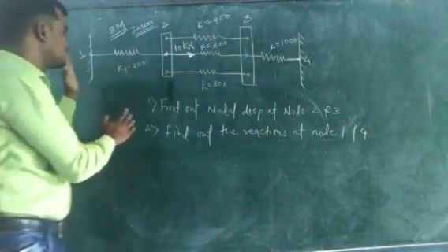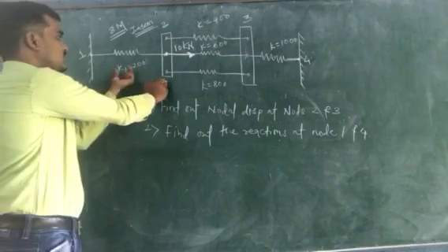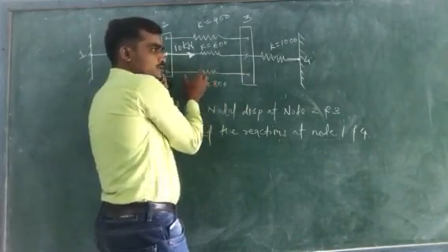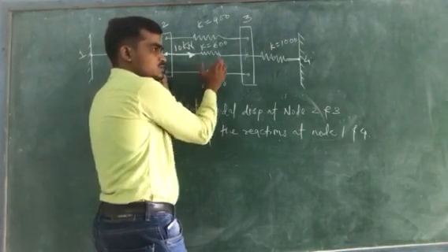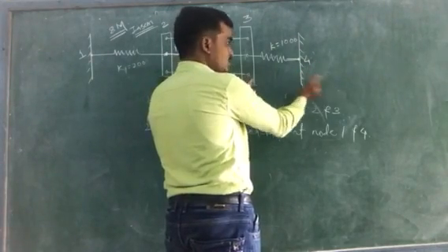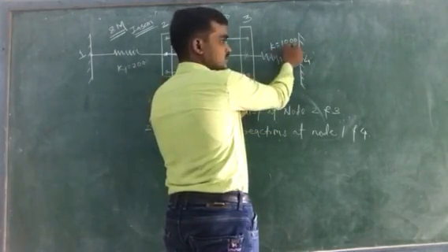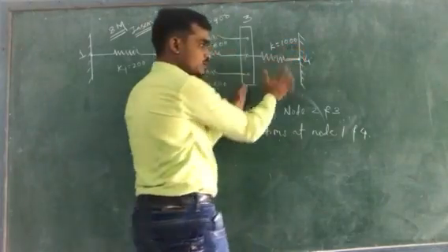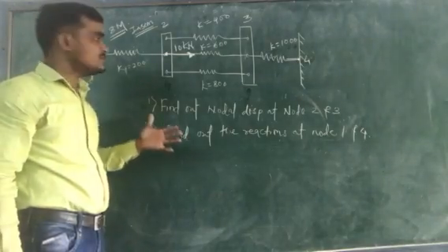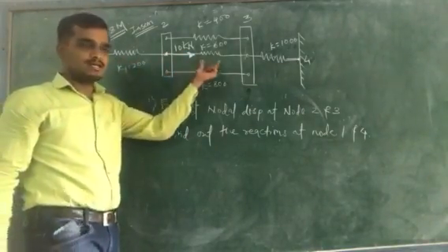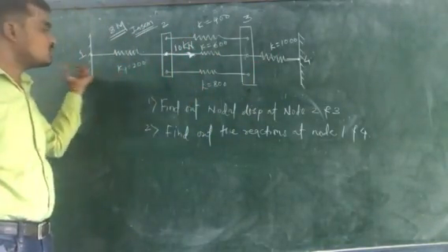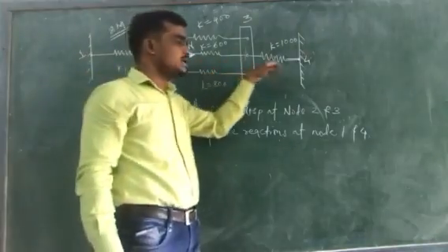Between the first and second node, the spring of magnitude 200 lies. Between node 2 and 3, a spring with equivalent spring constant k equal to 1800 will be there, and between the third and fourth node, there is a spring with spring constant 1000 Newton per meter. So it will become a 3 spring element system now: this is the first one, this is the second one, and this is the third one. For these 3 spring elements, there are 4 nodes: 1, 2, 3, and 4.